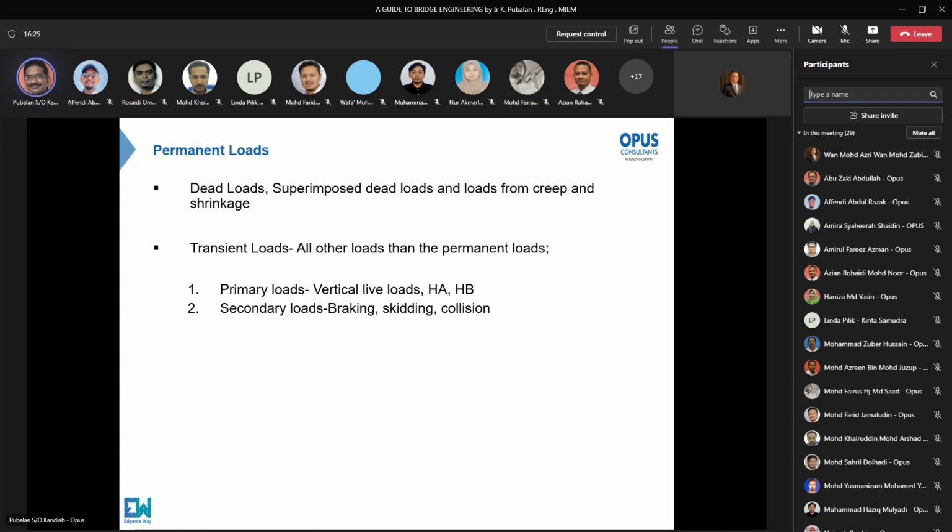Transient load means loads which can move. All right. So transient means it can move. So primary live load, you have HA and HB. Right. HA loads are called as normal loading. HA means normal. HB is abnormal loads. All right. So for bridges, you have HA and HB.